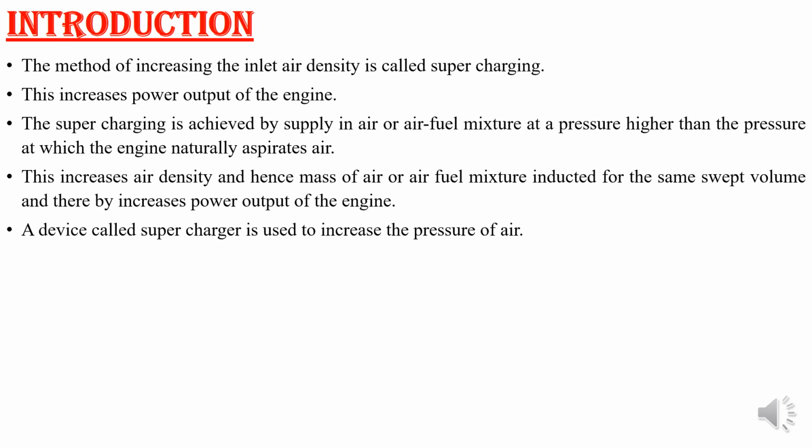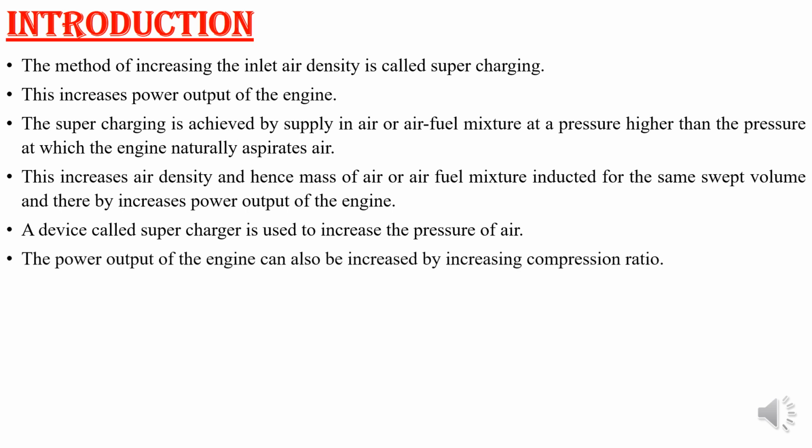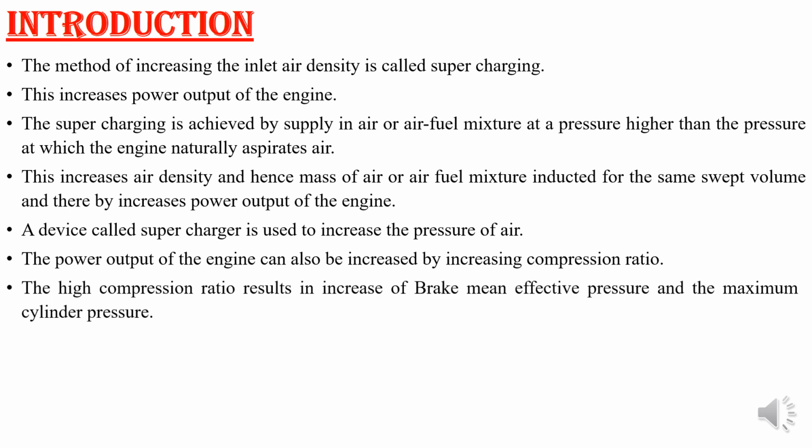However, this increase might be limited by cylinder pressure, because we can't go beyond a certain limit. The engine has to be designed for a particular pressure range or a maximum pressure limit. So we can't give too much air pressure inside the cylinder. It should be limited to the maximum cylinder pressure or maximum brake mean effective pressure. The rate of increase of maximum cylinder pressure should be less than the rate of increase in brake mean effective pressure in the supercharged engine.